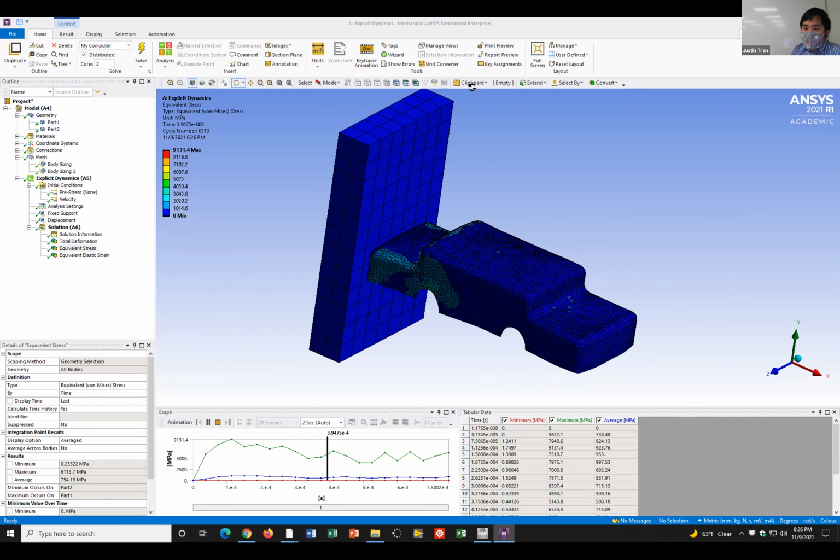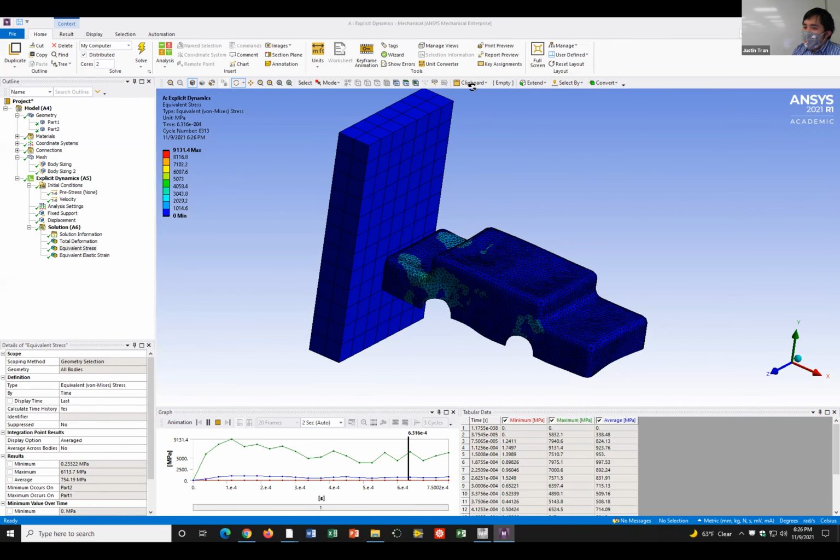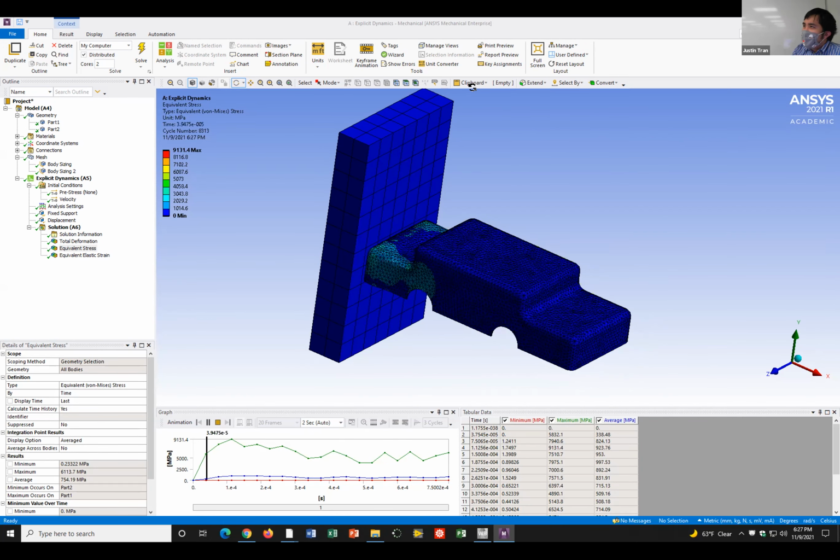Yeah, STEP file works good. IGS works really well too. STL also works, but I don't recommend STL because you lose a lot of information in the file form. STL is very compact, so it doesn't take up a lot of space. But if you're switching between SolidWorks and ANSYS, you want to transfer as much information as possible. Yeah, both STEP formats are just fine.